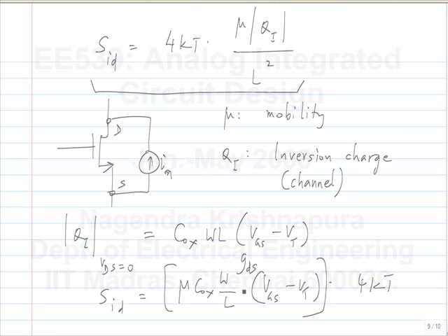The spectral density of noise current will always be of the form KT times some conductance, and spectral density of noise voltage will be KT times some resistance, with some constants before. It is intuitively satisfying because at 0 VDS it is a resistor, the mechanism of current transport is exactly like in a resistor, so the noise also is like what you see in a resistor.